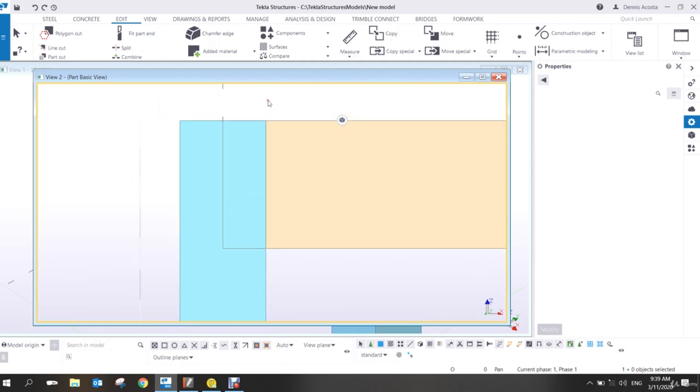Okay, so this time we are going to use the line cut. Like it says, this one is to create the shape in addition to fitting. Because the fitting has limitations, the line cut will complement the fitting. If I click this line cut, look what will happen. Same thing: select the object to be cut. The beam. And then pick the point on the cutting line. So Control 2. This one is the cutting line.